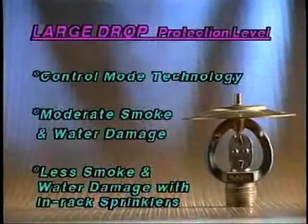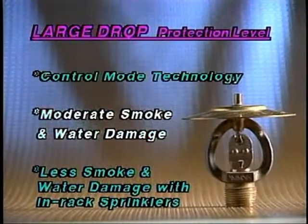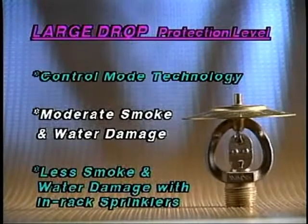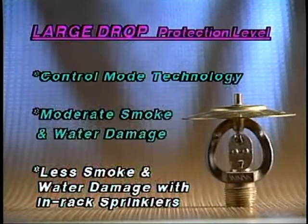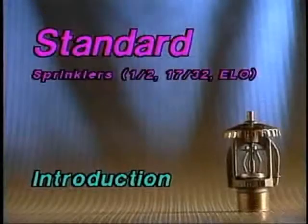During the testing of the large drop sprinkler, it was hoped it would be the first generation suppression mode sprinkler. Unfortunately, research showed it just wasn't quite up to the task. Large drop is control mode technology. So if you have them at the ceiling only, you can expect moderate smoke and water damage depending on the type and extent of the fire. When used in conjunction with in-rack sprinklers, you can expect less.